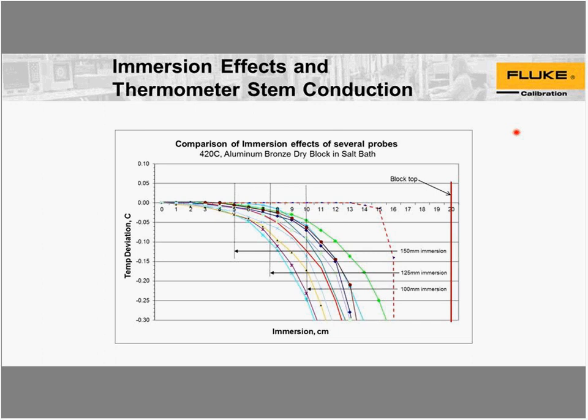It's attached to 3 or 4 lead wires going up to the handle, where they attach to the internal cable that goes to your readout device. You've got a thermometer there, an element of some length, and you really need to understand what that length is and its general position in that tube.